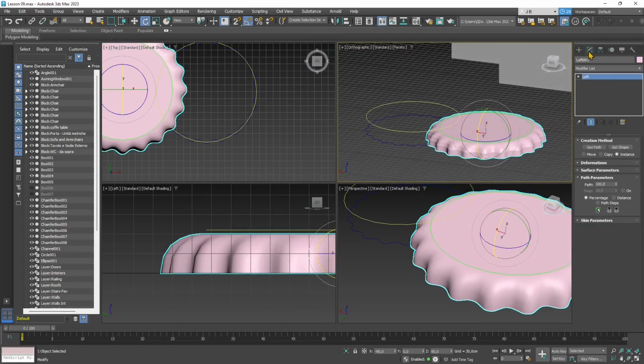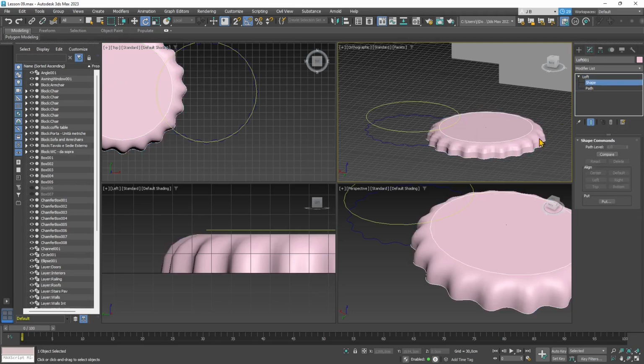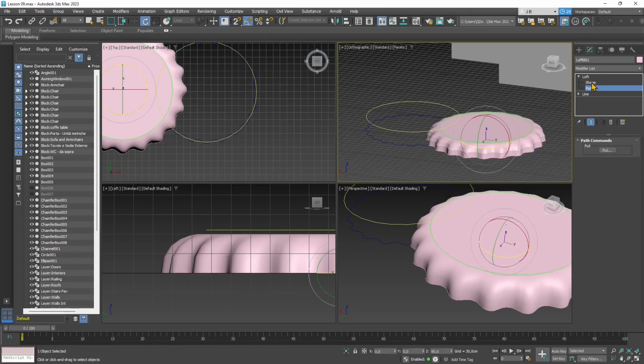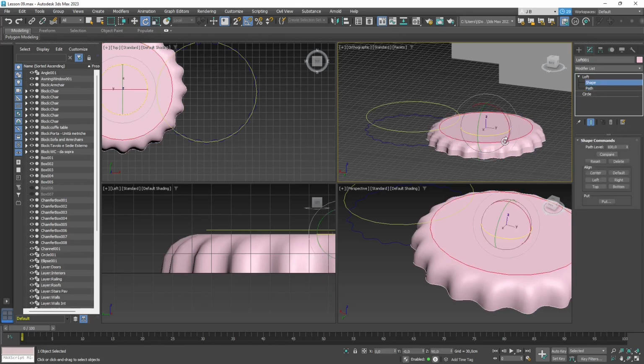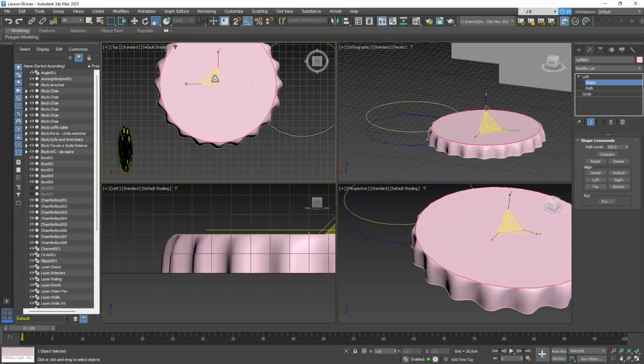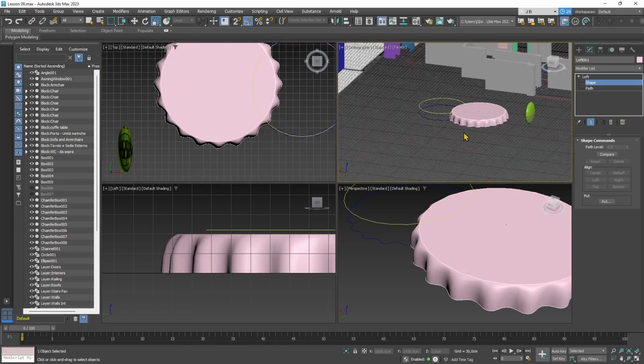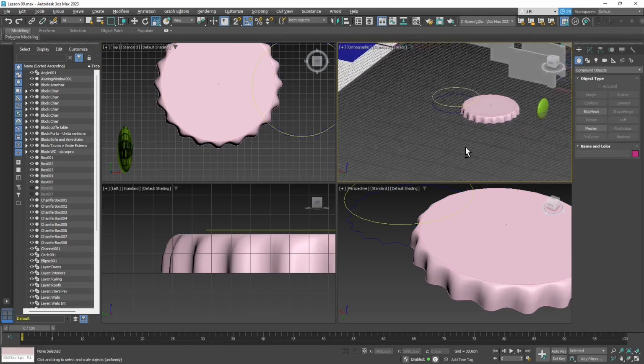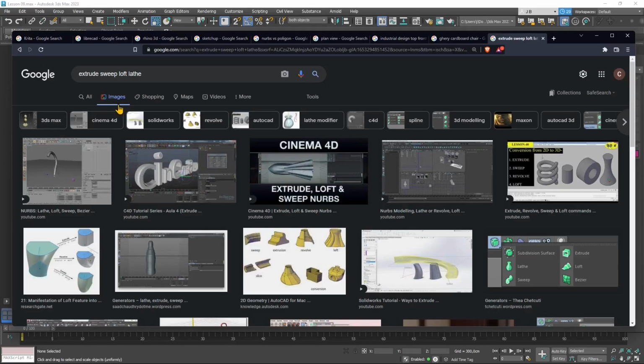Then we're gonna see more complex things like creating a pillar or creating a beam or column, an ancient column. You can create really anything with the Loft tool, but you need to have in mind precisely what you want to do and which will be the profiles, the sections that are gonna represent your object. Now I'm just scaling this circle. You can see I can access with the modifier panel, I can access the operands and I can change them.